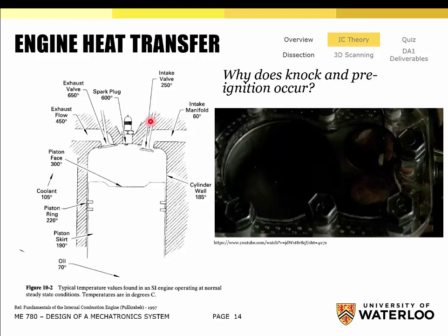It's going into the engine, but it's traveling through this hot intake system that's about the temperature of the cylinder wall, which is 185 degrees Celsius. The coolant temperature of this engine is 105 degrees Celsius, okay? So that 105 degrees Celsius is taking that air that started at between 0 and 30 and heating it up, not quite to 105, because what we're doing is vaporizing fuel in it that's cooling it down. That air is coming into the cylinder, it's getting inducted, it's going to get compressed,